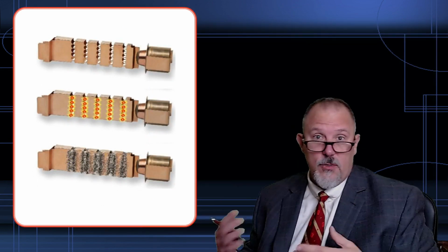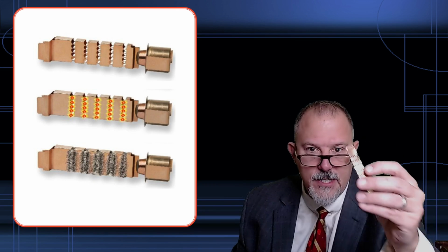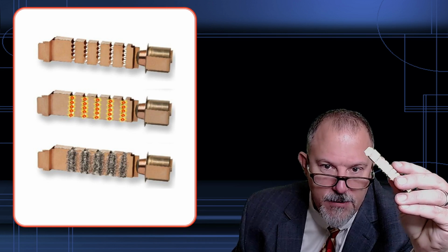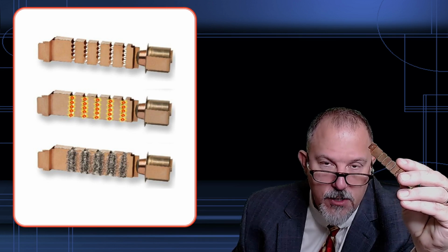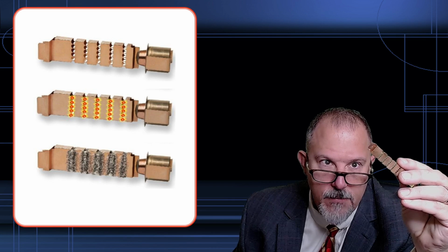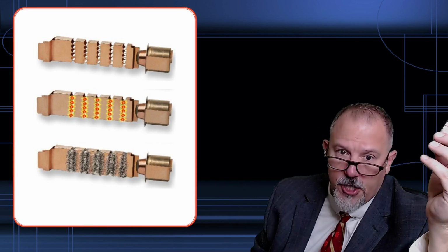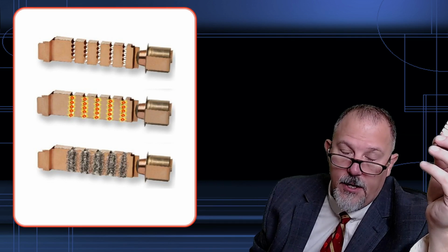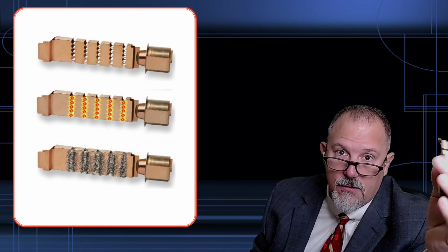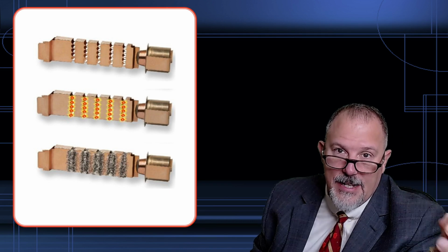Now, this is the short circuit. What happens during a short circuit? Very high fault currents flow through the device, and each of those little tiny pinch points explode. And what we're showing on this bottom one right here is the sand that turns into fulgurite that's insulating these units.